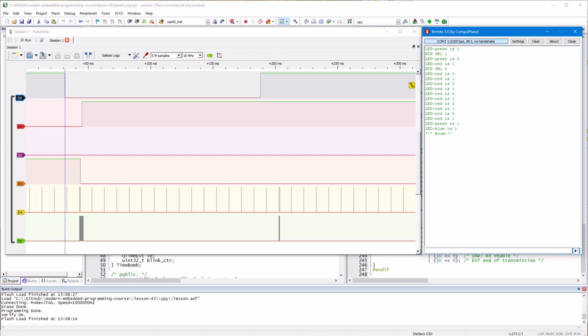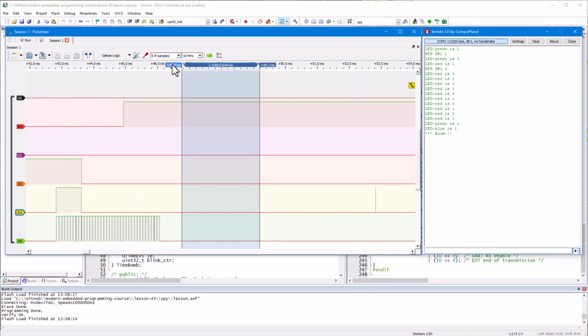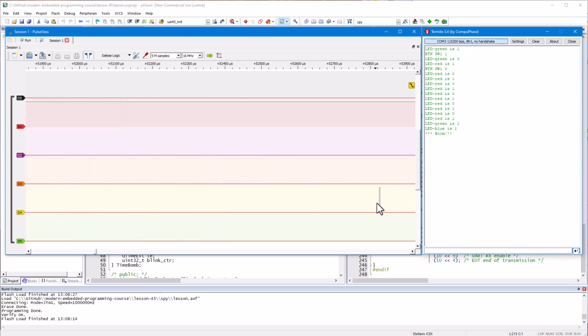Regarding the logic analyzer, trace D4 shows the activity of the SysTick ISR, which fires periodically, but one execution time is much longer. This is when the printf trace is produced, and it takes 0.78 milliseconds. That needs to be compared with the normal case of only 2 microseconds for the whole ISR. This means that printf extends the time by almost 400 times.